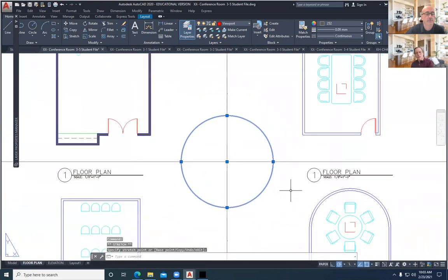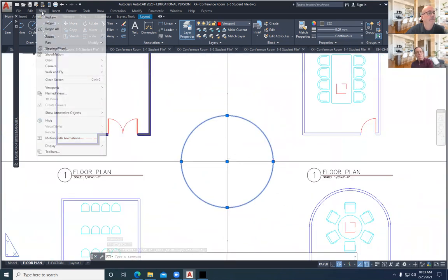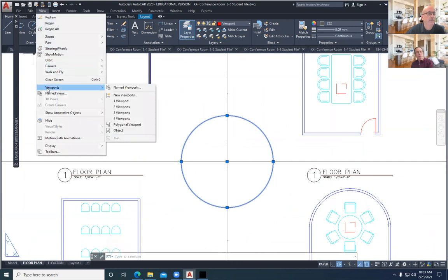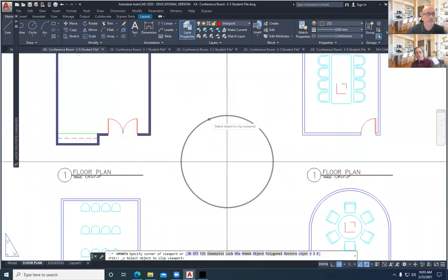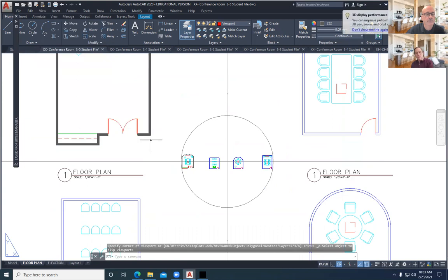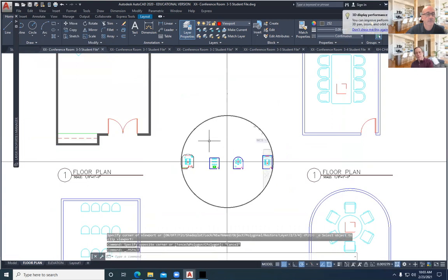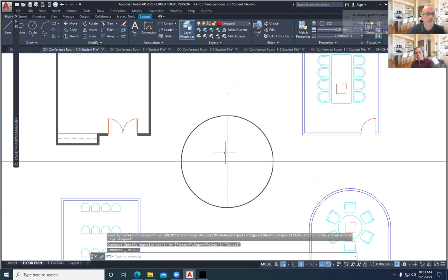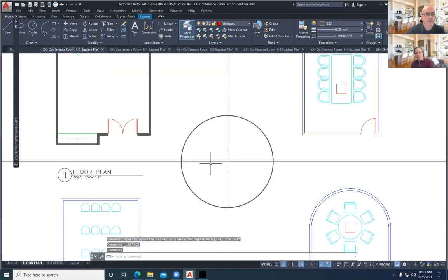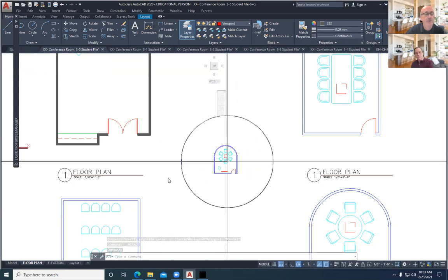And you want to go to viewports real quick. When you go to viewports, this is object on the bottom almost. Left click on it. Double click inside of it. You can zoom up into one of them, please, if you want, or two of them. Graphic card issues, but yeah, you can create these polygon shaped viewports.